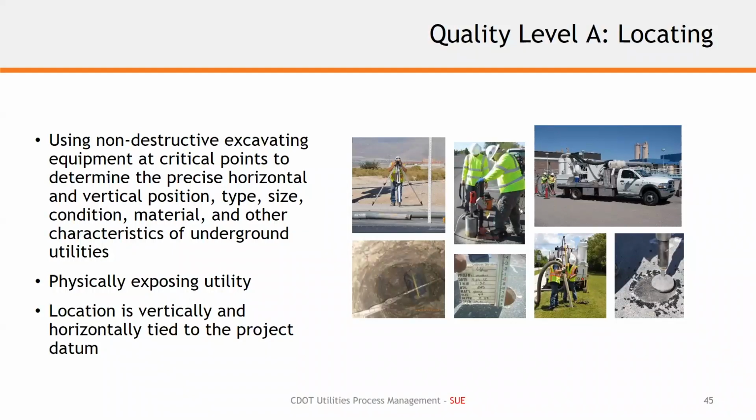And then the pictures on the right are just examples of test holing and locating those utilities and then patching them back, and some of the measure down cards that they have. So there are different ways to go about it. Each SUE vendor tackles it a little bit differently, but ultimately the end output is daylighting the utilities and having good information on where they are vertically. And again, down at the bottom, you'll see that this is a SUE function.